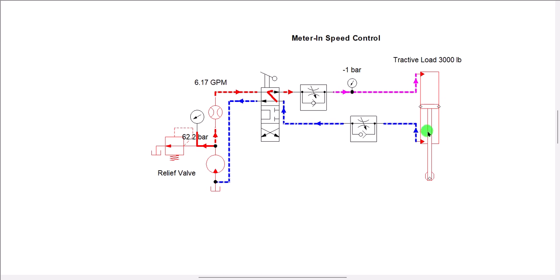So gravity will pull down the piston under such condition as fast as it can, because it literally falls like a free fall, because the fluid on the rod side doesn't pose any challenge to the piston's descent. So when this happens, due to this fast descent, a void is created above the piston,